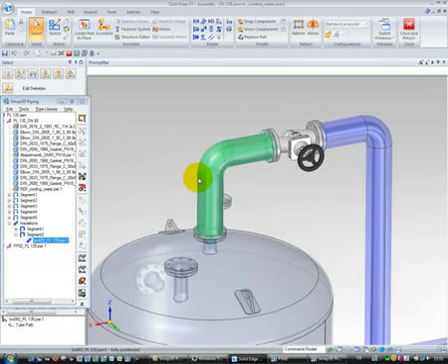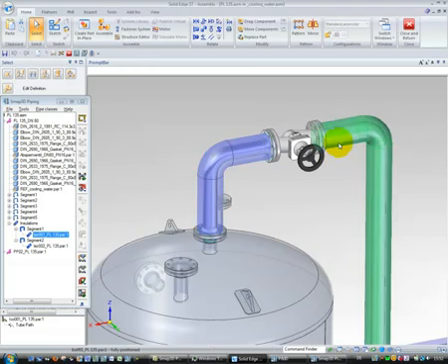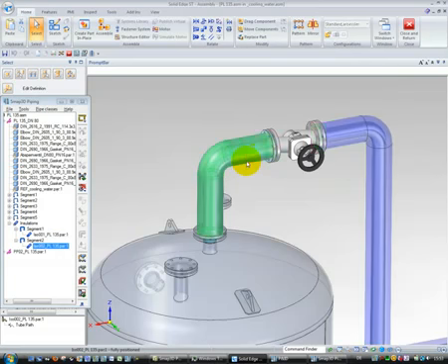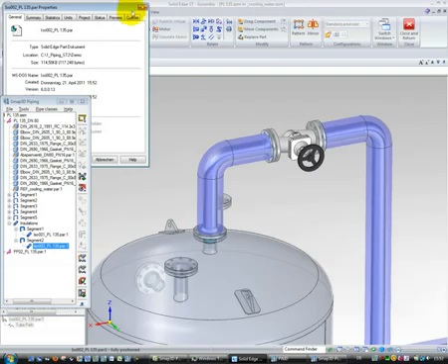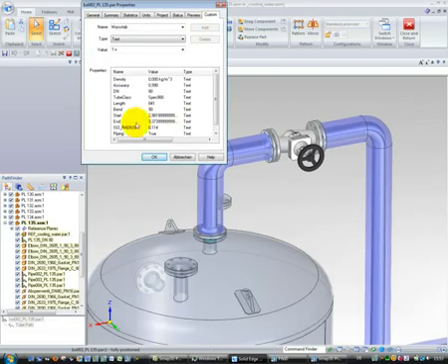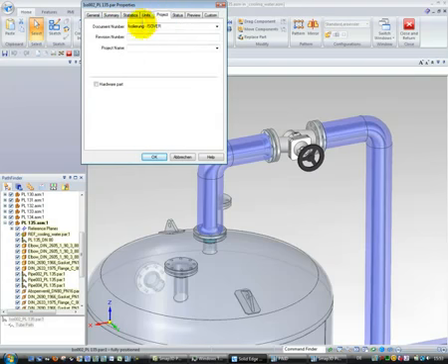Here separate insulation components are generated. The parameters and the geometry are delivered from the pipe spec we have assigned from the P&ID. And all these insulation parts also carry information about properties, length and so on, if it is prepared in the required way.